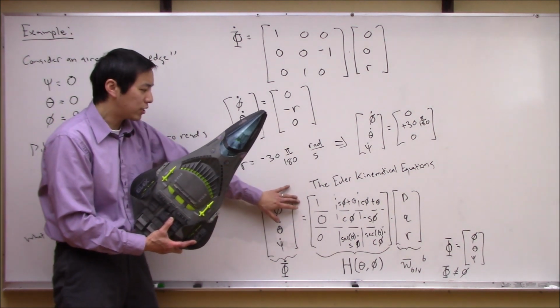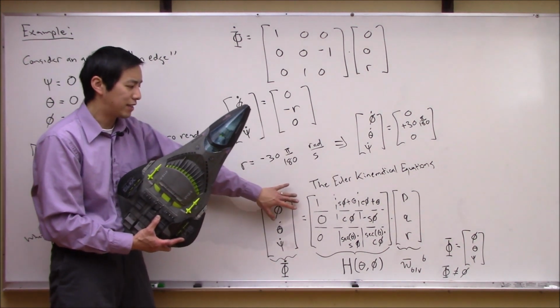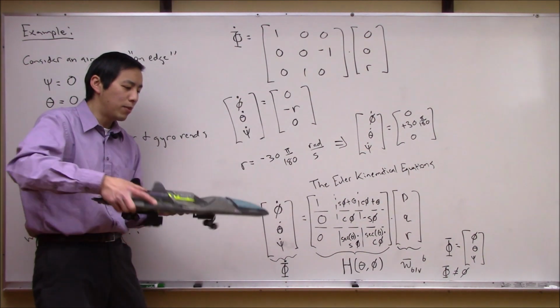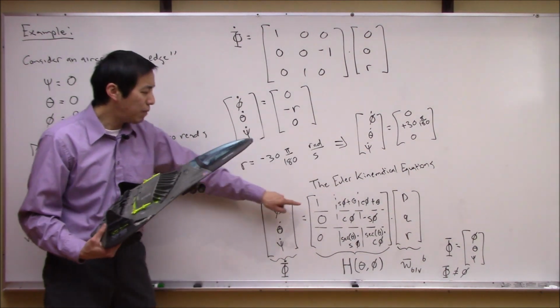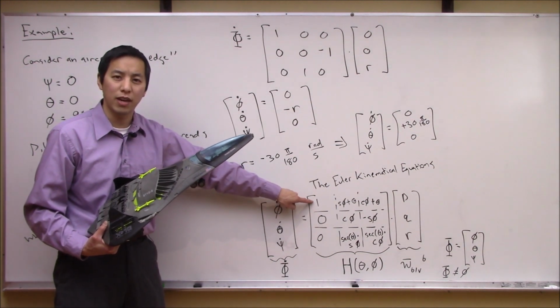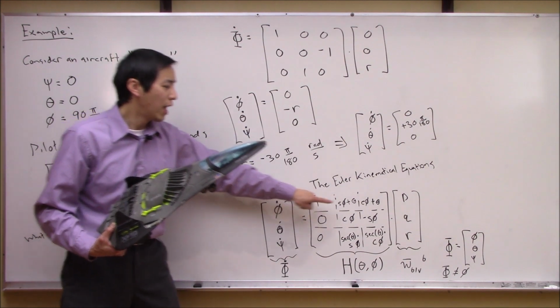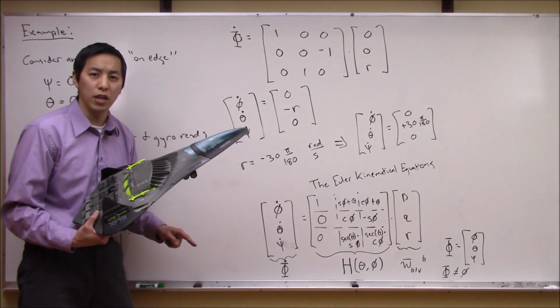The H matrix in this very simple case was obviously static, but this obviously begs the next question of what if the aircraft is maneuvering and changing? Well, that means that this H matrix is changing with time as well. So you actually have to recompute this at a fairly high rate and continually integrate with the rate gyros.